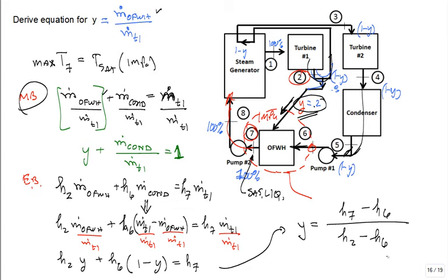Look good? So, again, if I divert Y, and H7 is based on being saturated liquid at that intermediate pressure, then I'll get the correct Y, which will give me the maximum benefit from this open feed water heater. Make sense?